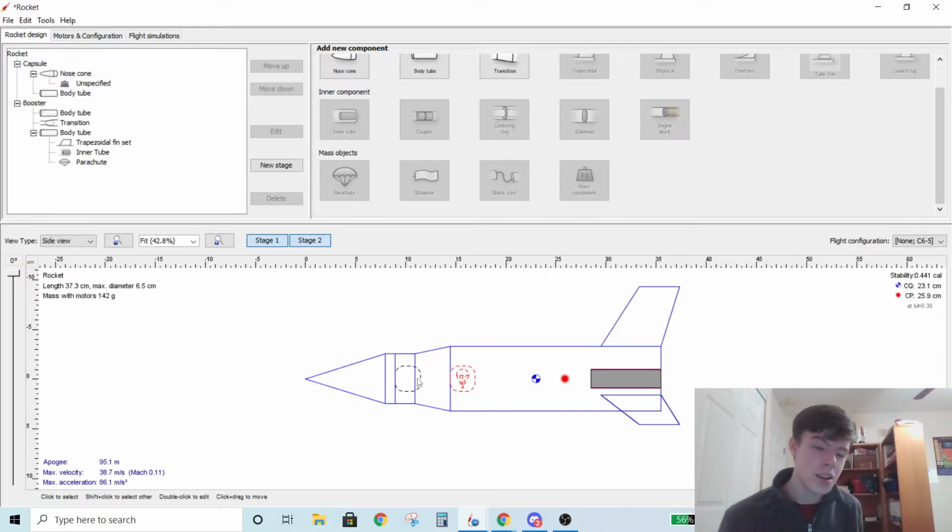because we're simulating the correct mass, which is once again an arbitrary mass, if you want to pick an actual mass, you can go through and fix this, and actually mess with mass numbers and get this mass correct, get this position correct. But that's not the point right now. That's easy for anyone to do. You just change masses and positions. As for center of pressure, OpenRocket is going to be far more accurate than you could ever hope to be manually. So you just let it calculate it. There's nothing else to that.